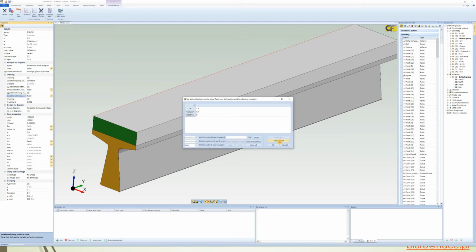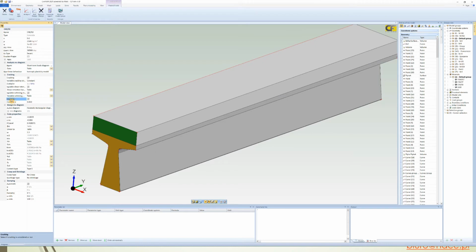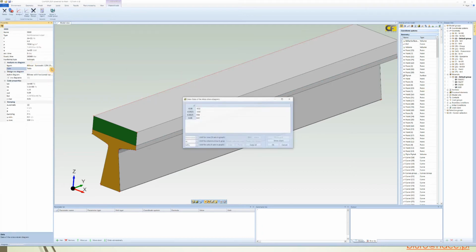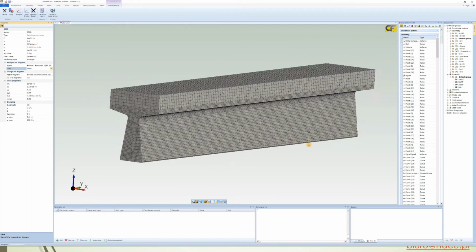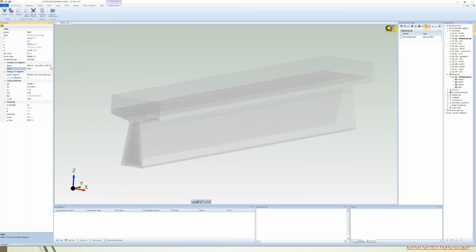And this is the post-cracking behavior. You can see the stress-strain relationship. Here in this case, for the post-cracking behavior, the crack stress is 3.5 megapascals with bilinear softening. For compression, the compression crushing failure is based on a compression strain of 0.35%. When the compression reaches that value, failure happens in that element. And the final data is for reinforcing bars, the bilinear law, as you can see there. So you can see it's a fully nonlinear model.